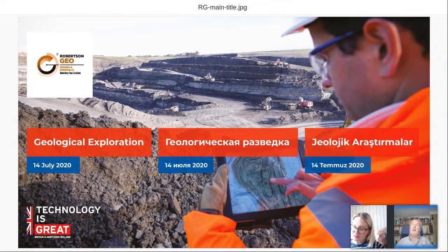At the top end, first of all, the depth limitation on the majority of tools is around 2,000 meters. There are some special circumstances for particular tools a little less than that. The camera that I mentioned we've developed is capable to 3,000 meters, and we will be producing it next year. I mentioned we're releasing some new products, so that will be capable of 125 degrees downhole conditions, and up to 3,000 meters depth.